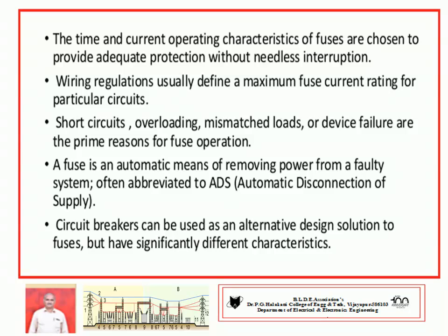It has inverse time current characteristics. Hence, as the load current increases, the time decreases. That is the idea here. Proper selection of fuse wire is also an important criterion. If your house carries a 10 ampere load, then we have to select a 10 ampere fuse wire. If we select less than 10 ampere, then it may blow out whenever any work is carried. If we select too high a current rating, then after burning your equipment, the fuse doesn't blow out. Hence, improper selection is very dangerous. Proper selection of fuse wire is a very important criterion.